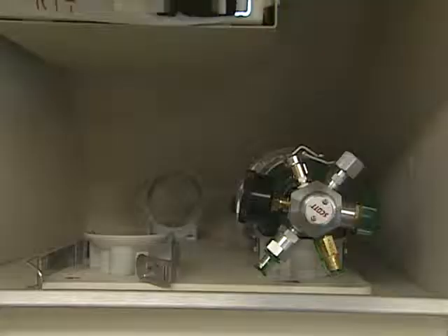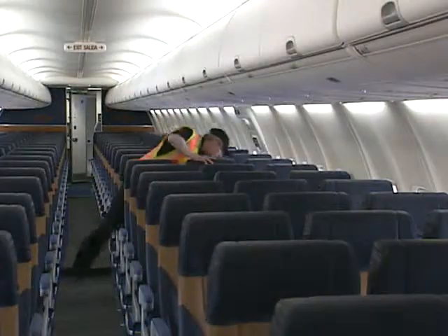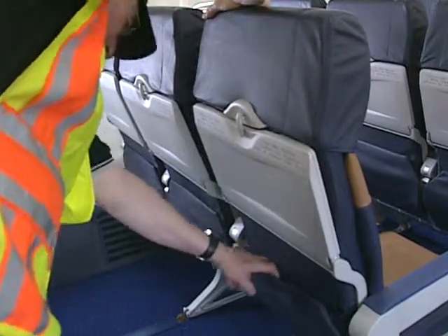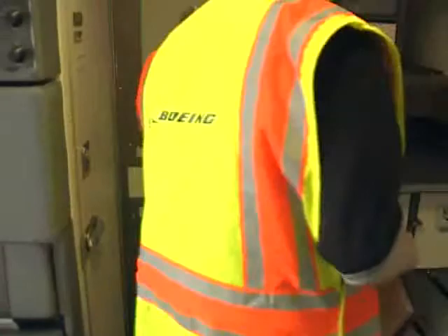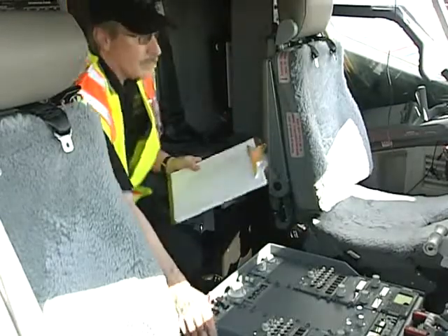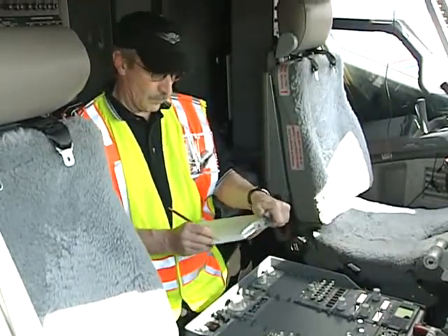Here's an example of something that's missing that we can replace. And check literature pockets and racks. Finally, check the flight deck. Our goal is to put the airplane in the predefined BEW configuration as closely as possible. This will minimize analytical adjustments that will need to later be applied to the scale weight to calculate the BEW.